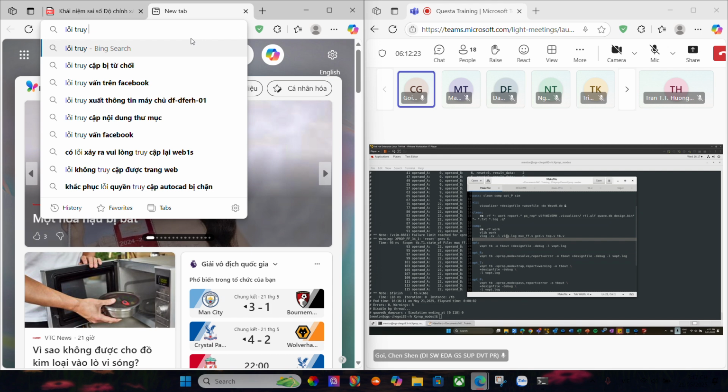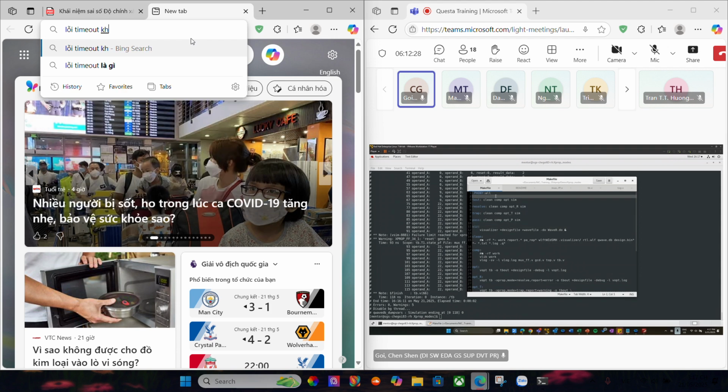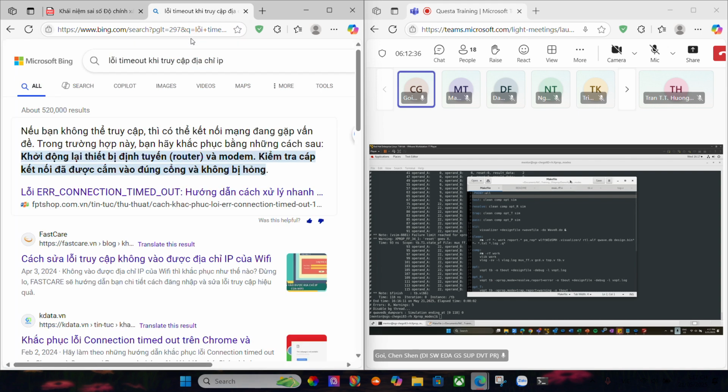Okay, so these are the labs for X propagation. We have included everything. This lab is particularly on each of the different X propagation modes, and you can see different outputs from each of these propagation modes. Depending on which kind of scenario you would prefer in your simulation result, you can choose either resolve, trap, or pass. So ideally, if you want to clean up your simulation design without any of the X as mentioned in the previous slide,